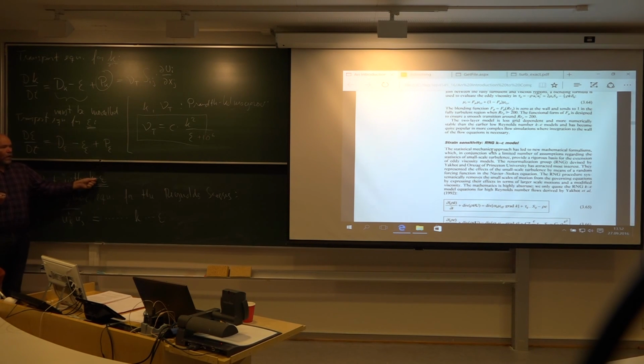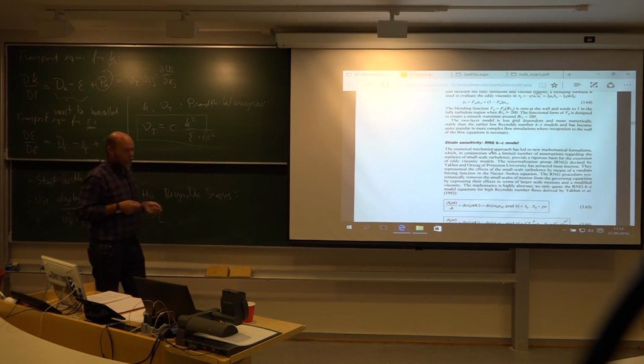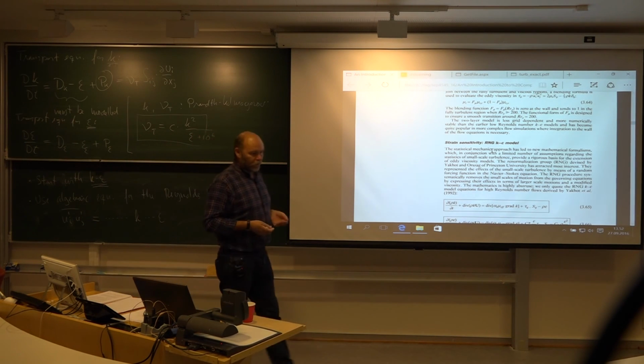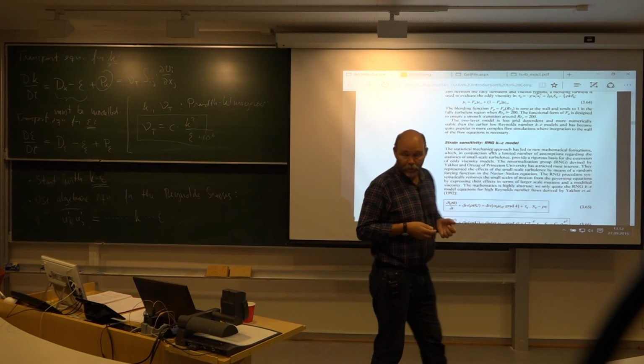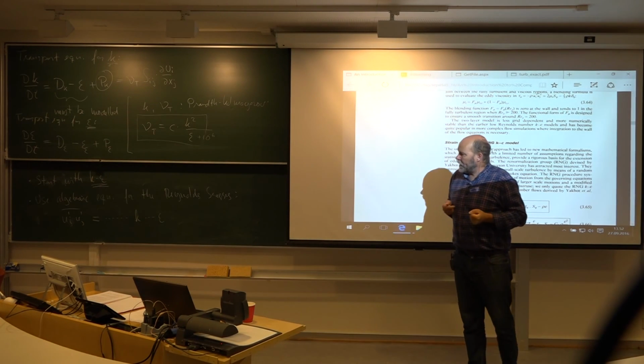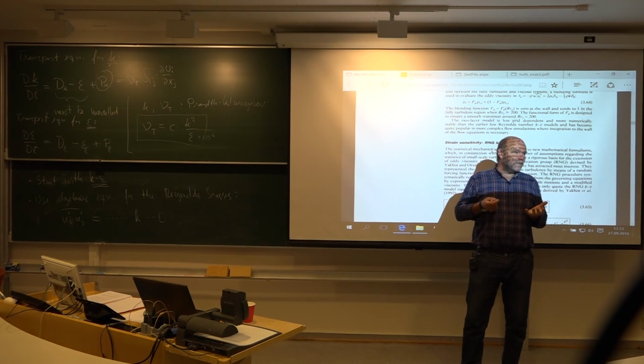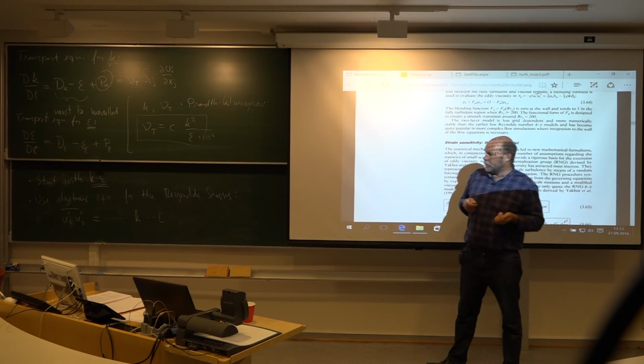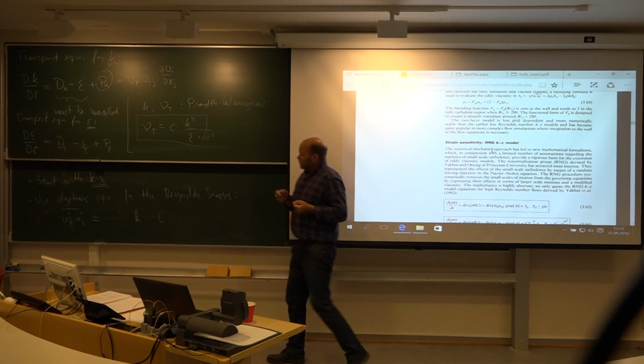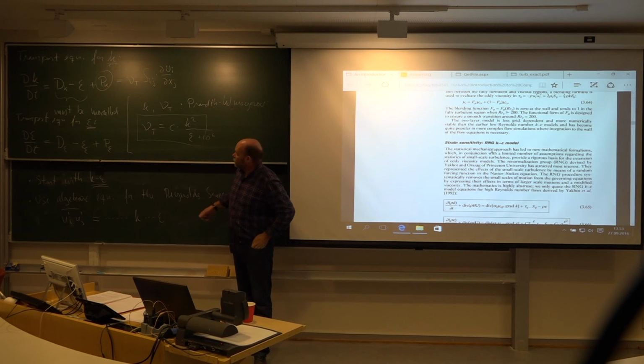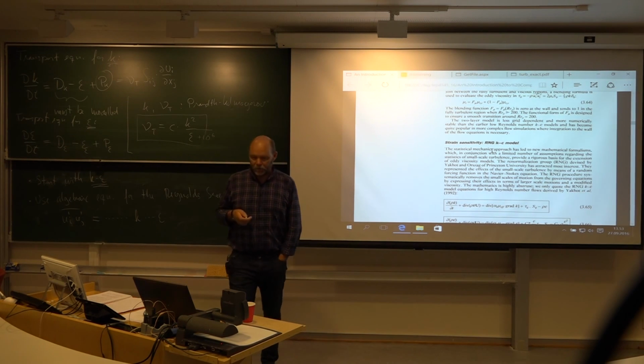And if you have a problem where we know that K epsilon has problems, like a big swirl or a rotating flow or a curved channel or something, you should just switch on an ASM. That's very cheap, and then it should cover much more of the physics, more correct. So an ASM is really something that is recommended.